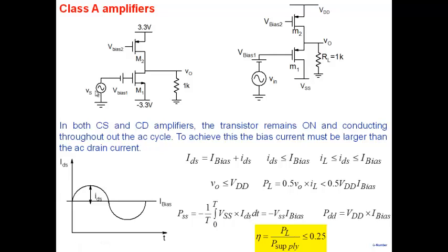Obviously, one of the features that you want is that you should take power from the supply only when you have something to deliver to the load. If you don't want to deliver anything to the load, why are you drawing anything from the supply? So this circuit has what we call standby power. Even when the circuit is not supposed to be working, not delivering any power, it has a very high standby power. The other thing is, interestingly, normally if you have to work, you get hot, right? You expend energy. But if you look at these transistors, when are these transistors hot?